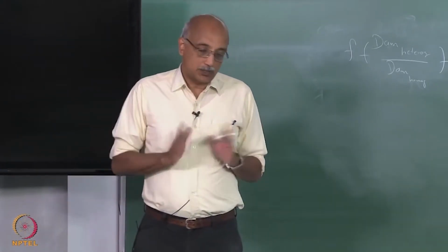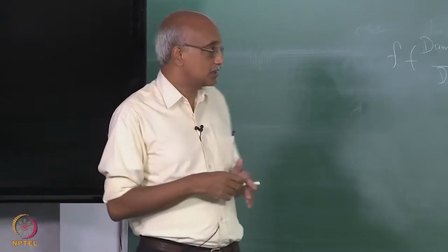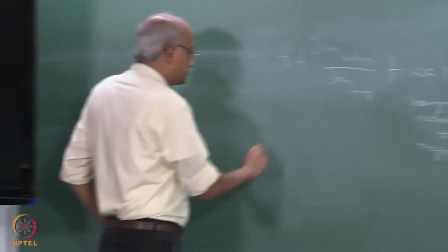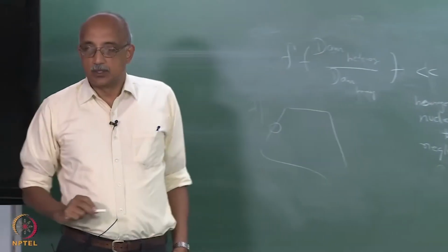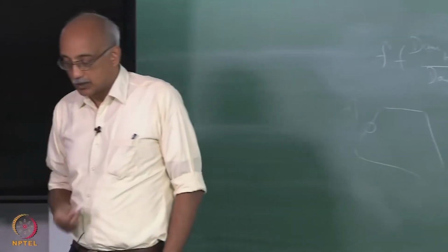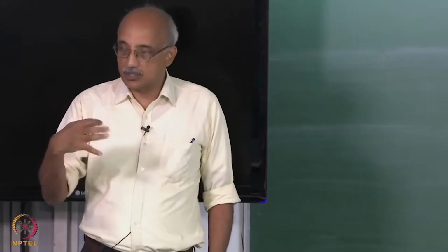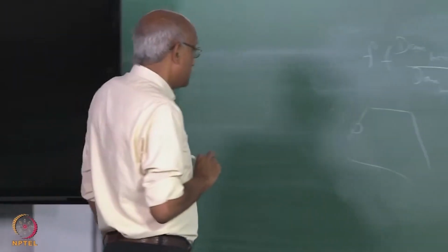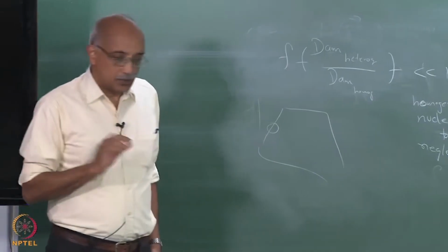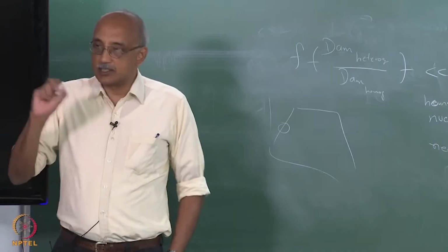Now, supposing you have decided you want an aerosol CVD reactor and you have chosen the conditions so that you are in this region somewhere, and you have chosen your Damköhler numbers so that yes, there is a high probability of homogeneous nucleation happening and producing these fine particles, then there are two challenges. One is, how do you manage the temperature gradient?